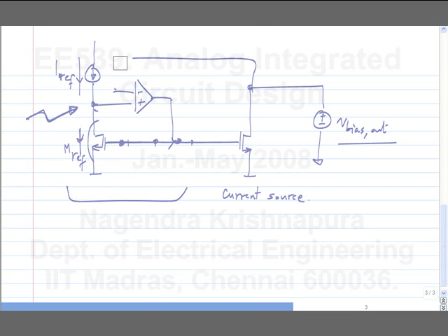We tried a straight connection, that seems not to do the job. Then we tried a voltage follower, that also doesn't do the job. What's the next complicated circuit? We know how to make op-amps now, right? We use the simplest op-amp that we know. What is the simplest op-amp we know of so far? The single stage differential pair. Will I use an NMOS or a PMOS differential pair here? Why?